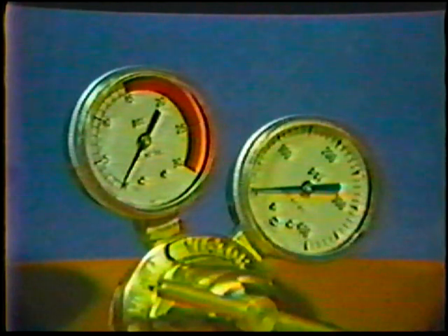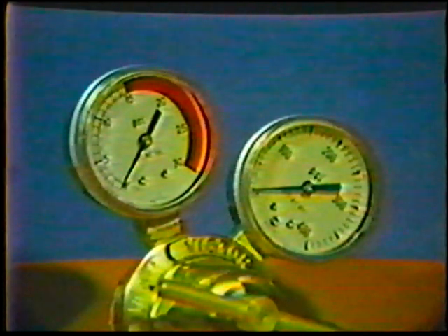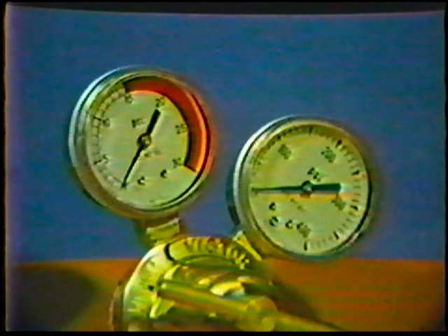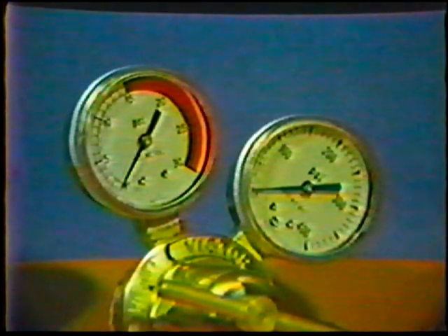Both oxygen and acetylene can be very hazardous if the cylinders are damaged or used improperly. Although the pressures used from the supplies are relatively low, the supplies themselves are quite high in pressure, and regulators must be used to reduce pressures to safe working levels. The pressure gauges and regulators are similar for both oxygen and acetylene and perform the same job. The gauges indicate the tank pressure and the working pressure, which is the pressure needed for a particular tip size.